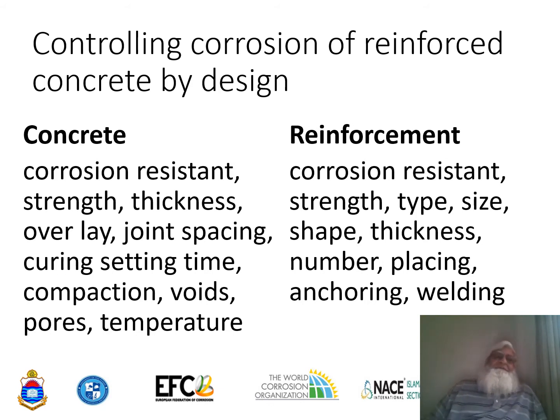The concrete must be corrosion resistant. Usually, Portland cement is not corrosion resistant. It can develop corrosion, so it has to be mixed with other additives or another type of cement called polymer cement, which can increase the resistance of the concrete to corrosion. Strength is another factor: the stronger the concrete, the less vulnerable to deterioration. In the same way, as you increase thickness, the strength of the concrete increases, and that is how you can prevent concrete deterioration.